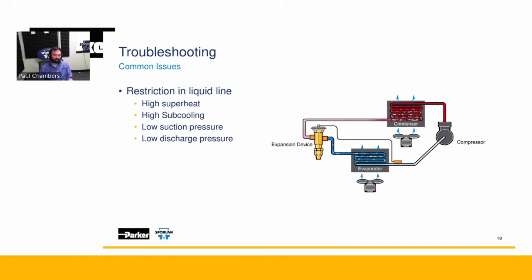You also might see those same debris and gunk clog up a filter dryer. So we often put a filter dryer in the liquid line to catch that debris, and catch any moisture you might have left in the system, because we were very careful when we chose our refrigerant. It had specific properties. Like I said, each one had a different boiling point. Each one's going to have a different map on a pressure enthalpy diagram. We chose a specific refrigerant for a specific reason, so we would know when it boils and when it doesn't. Well, if I start mixing those, it's not going to work well.